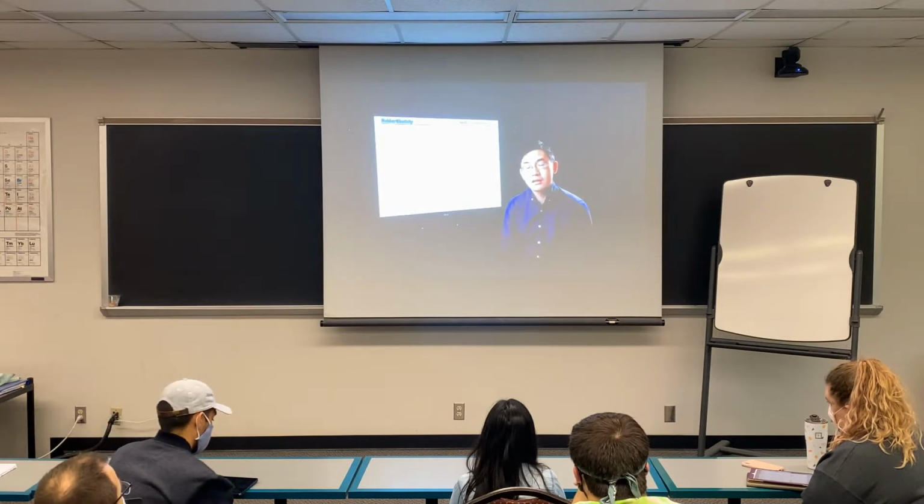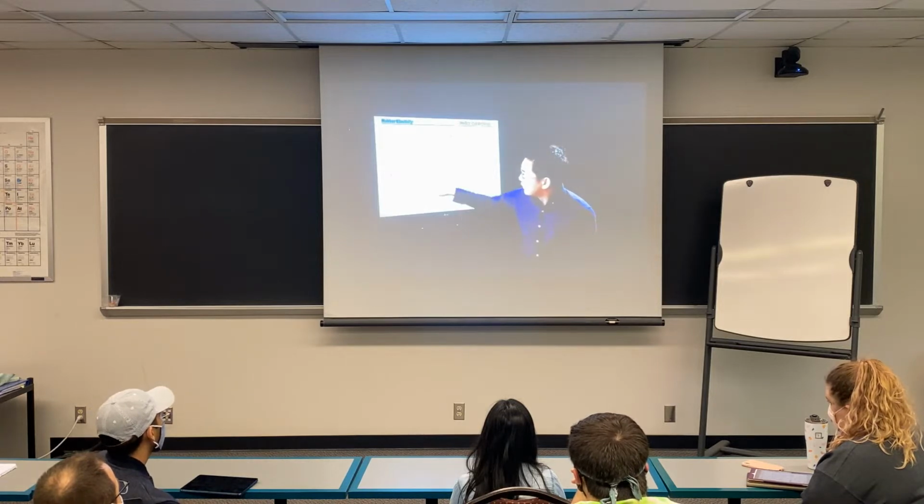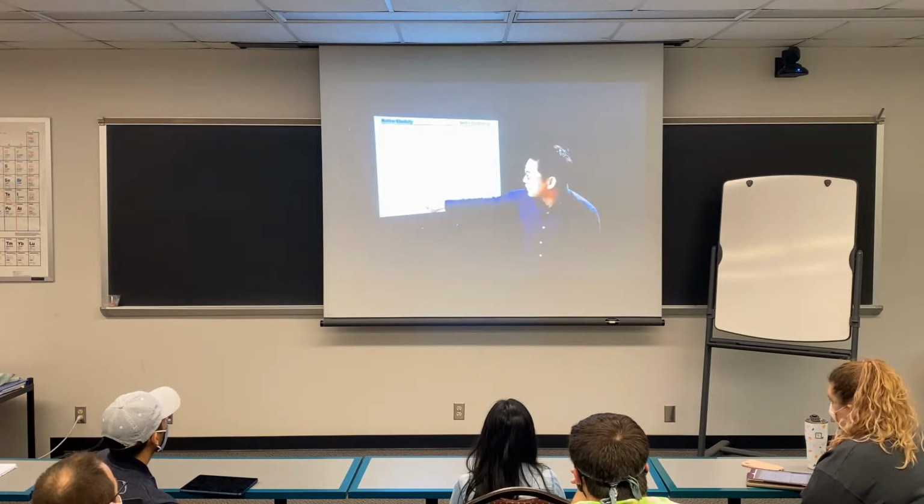This would result in an increase of the modulus of your material. This is partially the reason why there is a rapid increase; a lot of crystallization happens here. Meanwhile, there is a lot of deviation from the Gaussian theory, so this is something you should keep in mind when you use this theory.